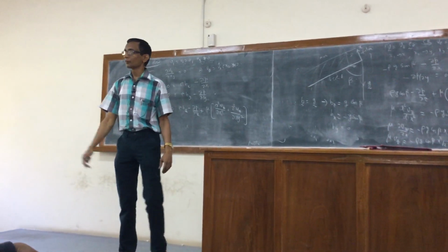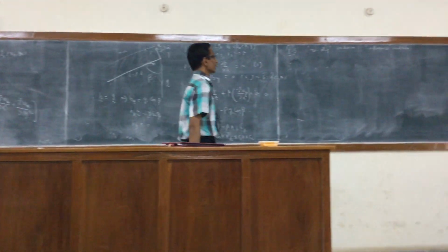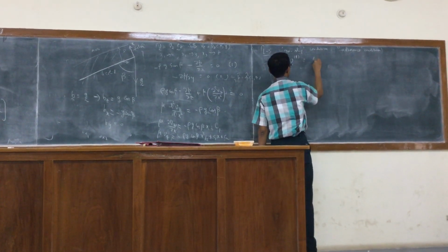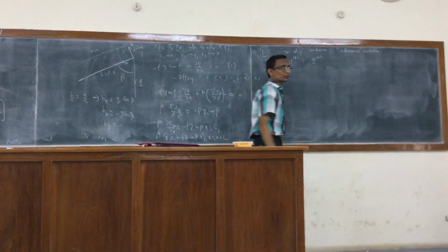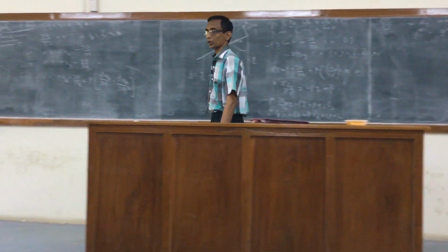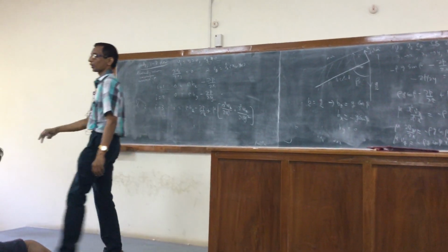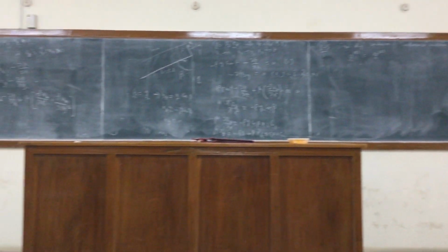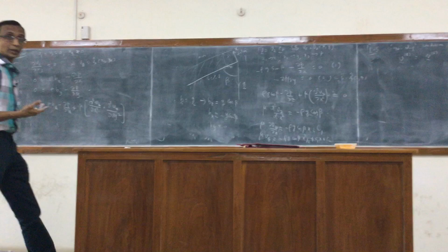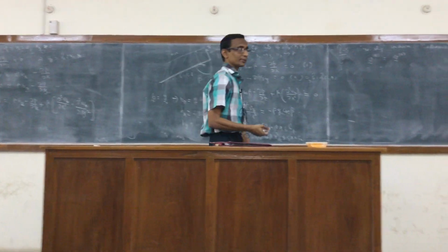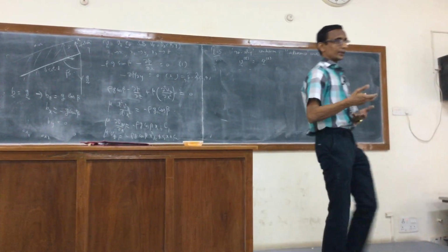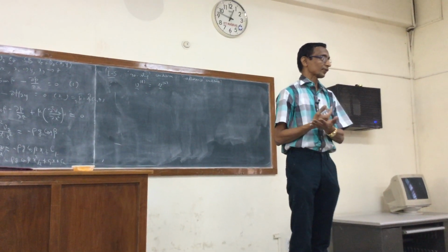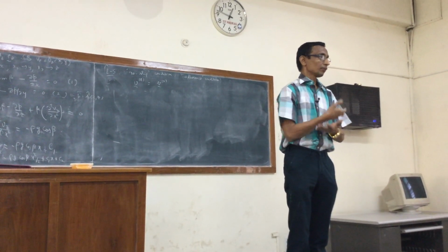So in which case, what we say is that the V of the liquid is equal to V of the solid. Here, of course, I need only one component. I am writing the general expression for the no slip condition, where all three components might be present. Right? So what it means is that effectively the fluid adheres to the solid surface. That means it has the same velocity as the velocity of the solid. The solid is also moving.